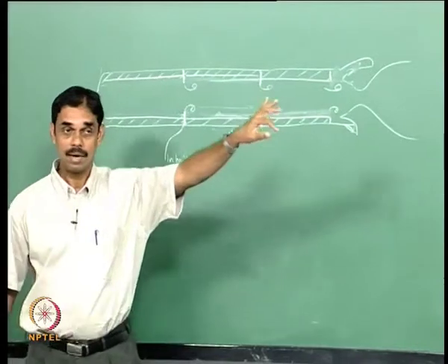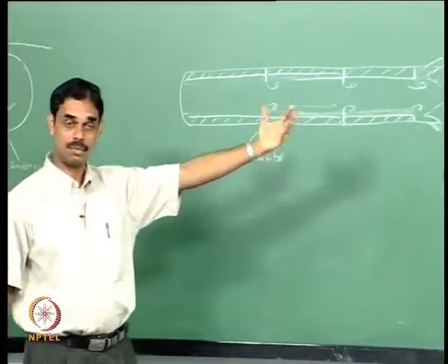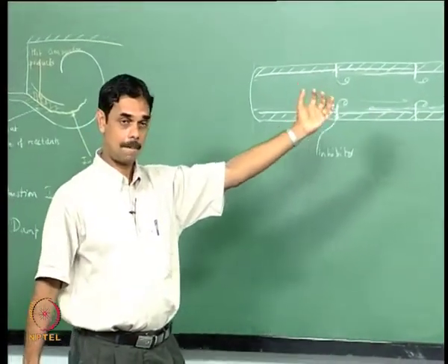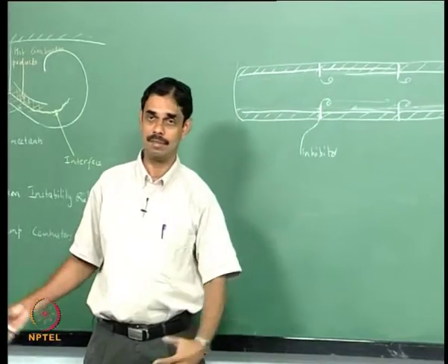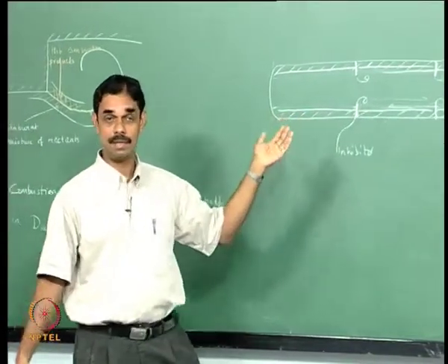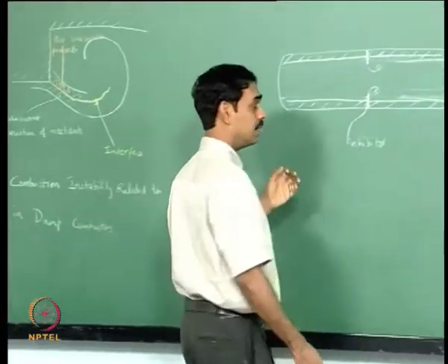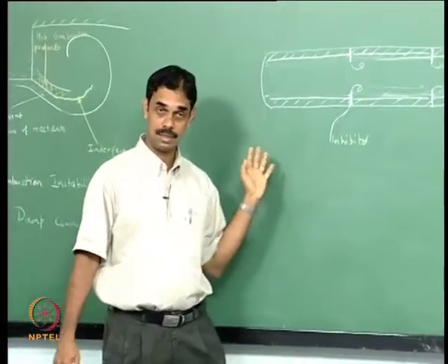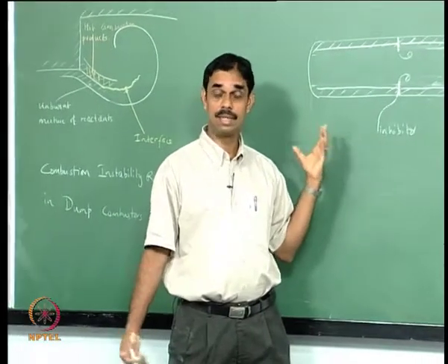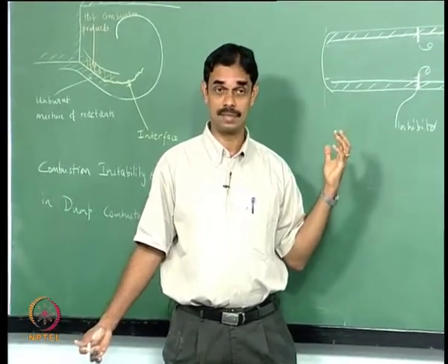So there are many different ways in which this vortex sound can be produced. These things have very high mean pressure, like 60 bar and so on, so even if you have a very small fraction of the mean pressure as fluctuating pressure, you still have the possibility to create enough structural damage.